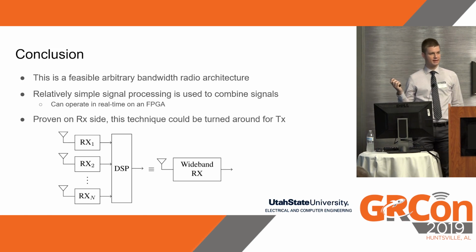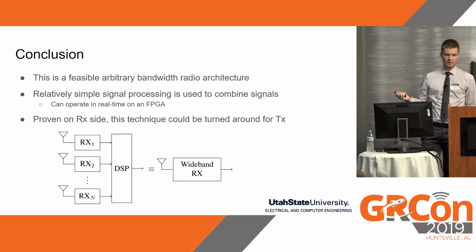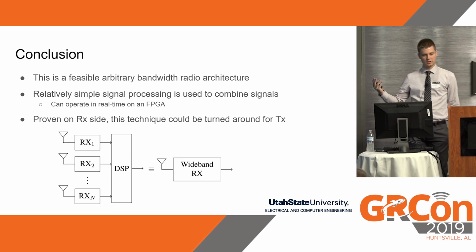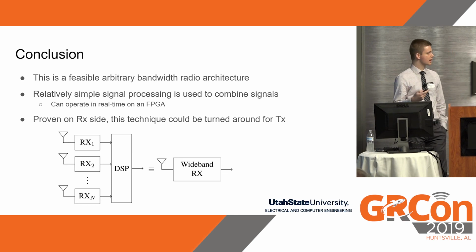On the TX side, it's essentially the same thing. One nice feature of the 9361s is there's an internal loopback that you can enable so that when you're transmitting, you can receive on one of the receive channels the same signal you're transmitting, and you could use that to synchronize the signals in the exact same way.